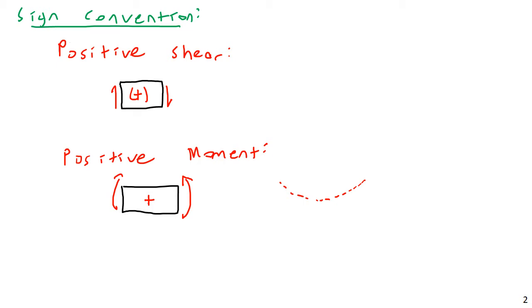There are definitely times where you can have negative bending in beams, especially when you have a continuous beam that passes over multiple spans. Imagine one beam that passes over a series of columns. Let me draw this out.